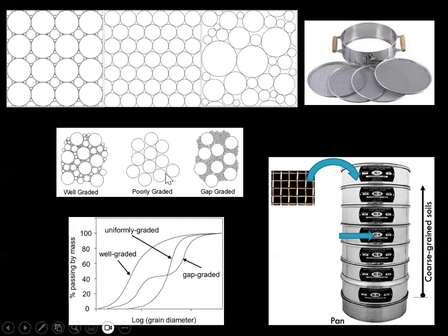So why? Well, suppose you have just one size aggregate. You see this one says poorly graded, or if you look down here in this graph, the one that says uniformly graded. That's the same thing, because uniform is like uni, like one form, like one size. The one up here is labeled poorly graded. Why would that be poor? Well, you see these big old gaps between the aggregate. Now that's going to be filled by your Portland cement.